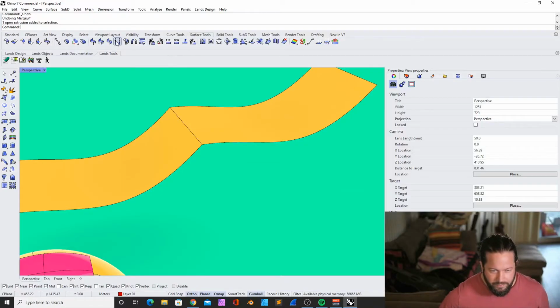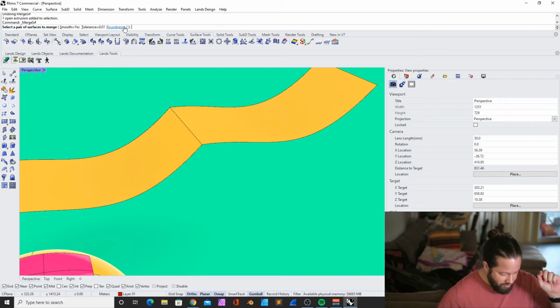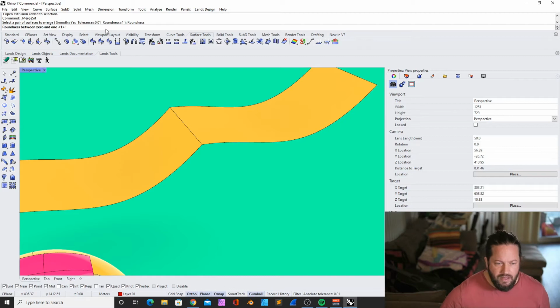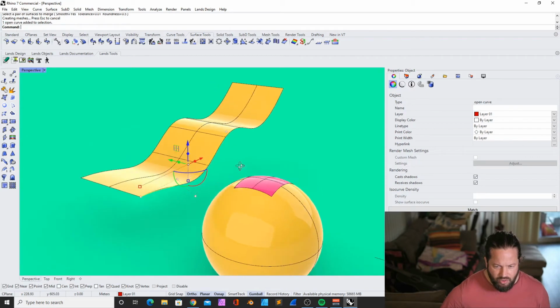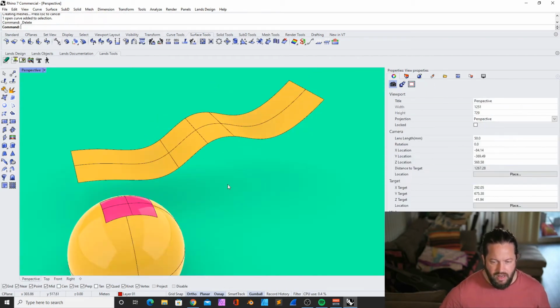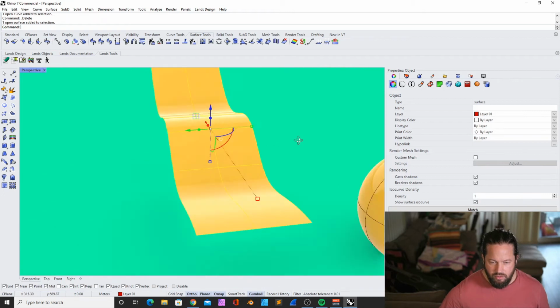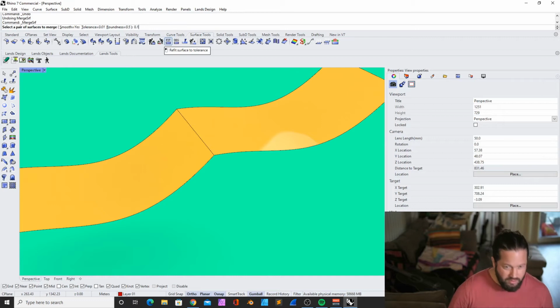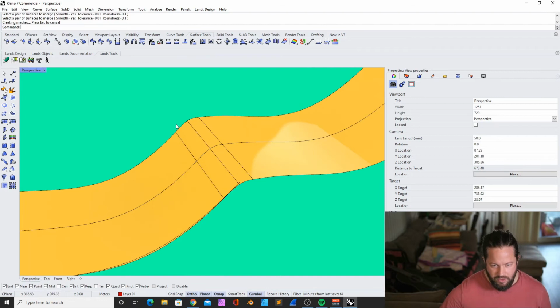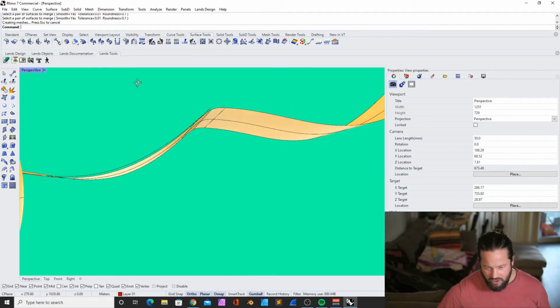Okay, so we can merge surfaces, but you have to set the roundness. Roundness 1 means more round, more curve. You can only set it between 0 and 1. Let's set it to 0.5. Select the surface, and they need to connect. That shows this is the original line I drew. But yeah, it creates one surface. Let's go back and let's try another roundness. Let's try 0.1. Select, and then there's much more edge to it.